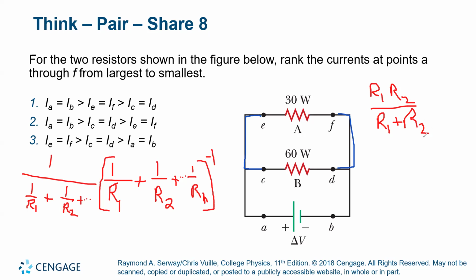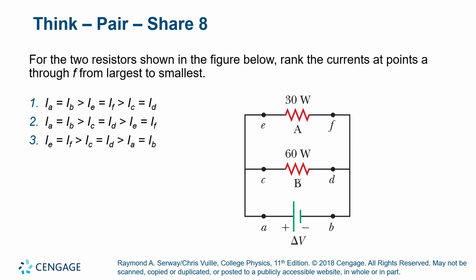So this is an important difference. Resistors in parallel will act like capacitors in series as far as their formula goes. They're not the same element, so I don't want to imply that they act physically the same way. They act very differently, but the math that you would use is the same. Okay, so we have this formula for simplifying this circuit,